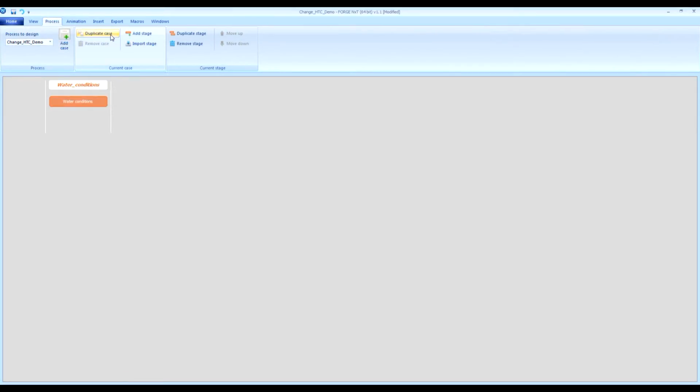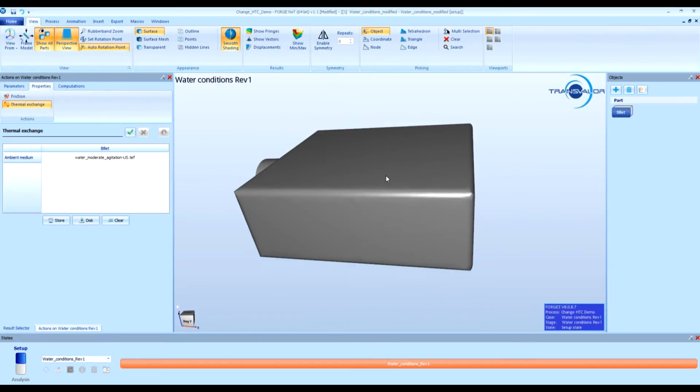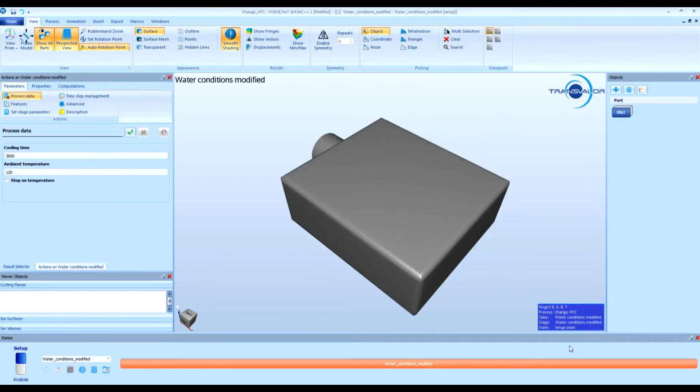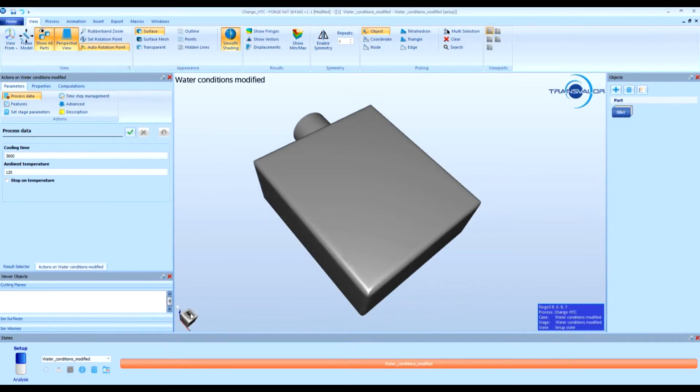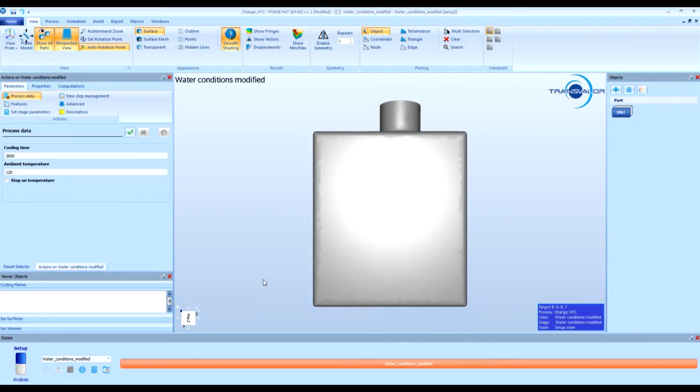Here we see how to copy and paste an existing project to make a new revision. The surface boundary condition set is available through the Advanced tab of the object considered. Here the fuel tank. The user adds a set and specifies the location of set where the conditions will be applied. Once the surface selected, here with a plane, the user picks the specific condition to apply on this set.